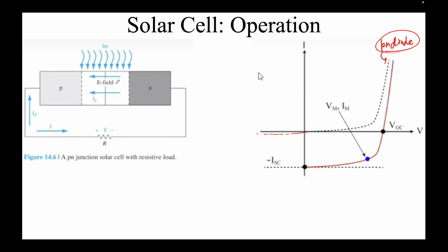What I'm interested in finding out is the excess number of holes that are generated. So now I'm considering a p plus n junction. From this analysis onwards, it's a p plus n junction. So in the p plus n junction, we only talk about holes. Why? Because the concentration is so large that they are going to dominate the mechanism over here. We'll generalize this a bit more, but let's just focus on holes for now.